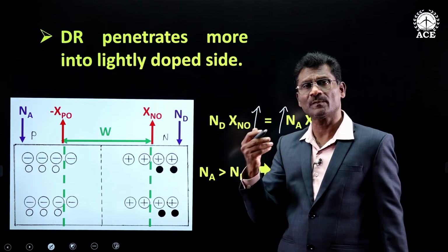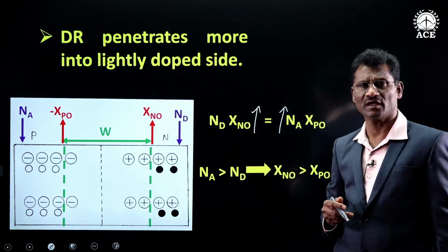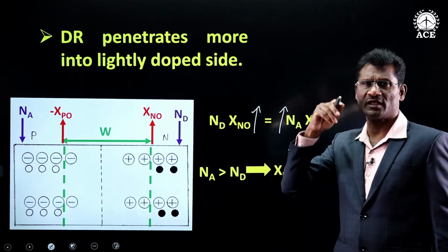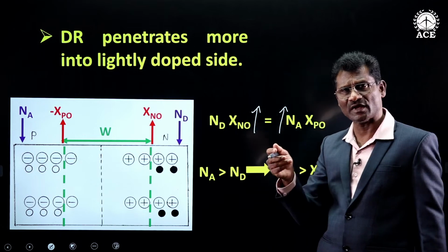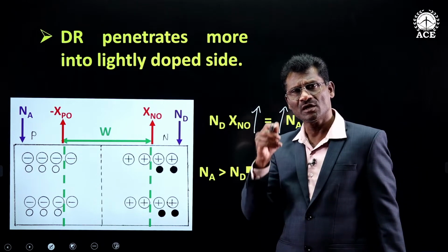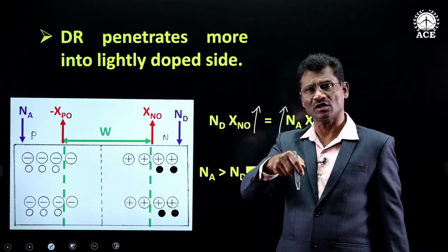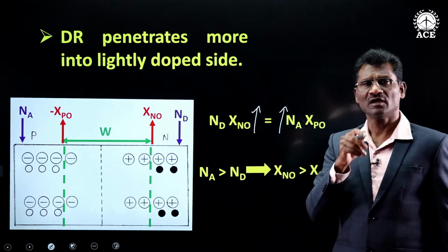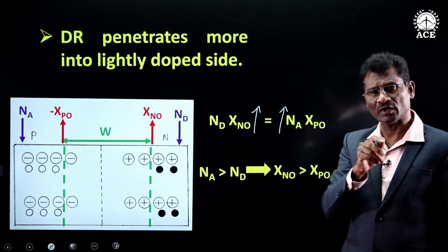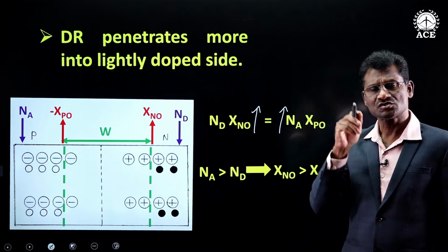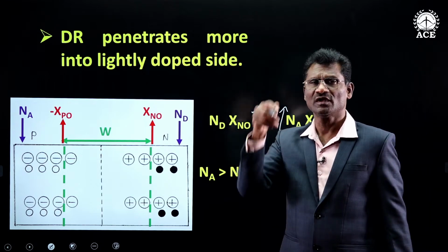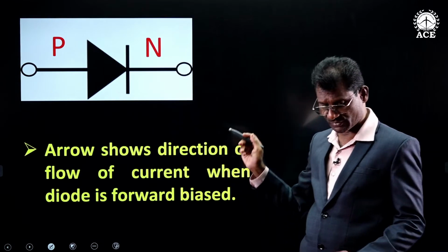Top and bottom we have P plus gate. That P plus gate and n channel, if it is reverse biased, depletion region penetrates more into channel. Why? Because that channel n side is slightly doped when compared to P plus side. So that concept of pinch off is again explained using this statement.